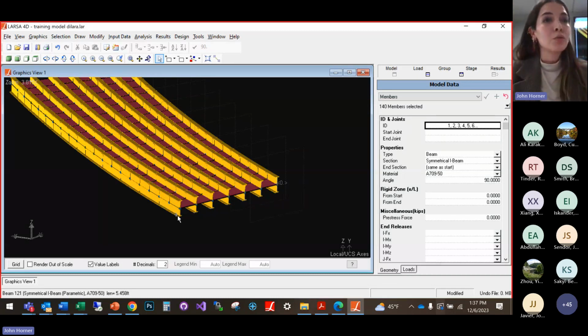And this extrusion tool will copy that girder also. We tell it a repetition, and it will copy that girder 6 times because we enter 6 repetitions. And between these repetitions, we select shell elements, and shell elements will be created between the copied girders. That's what this extrusion tool did.